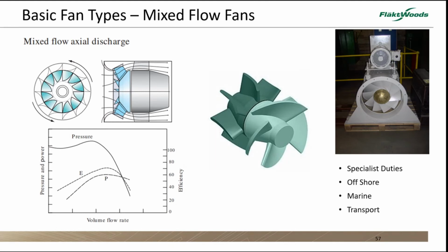The mixed flow fan has a little bit more of an interesting history. This shows one of the Flakt Woods mixed flow fans. They were developed specifically for the North Sea oil platform market, because these fans run very, very quickly. They have a high volume and pressure characteristic, but they're extremely noisy, as any fan that's run at very high speed will be. But when your construction restraints are on the square meterage of the floor, then the smallest fan that you can possibly get to do duty has some advantage.